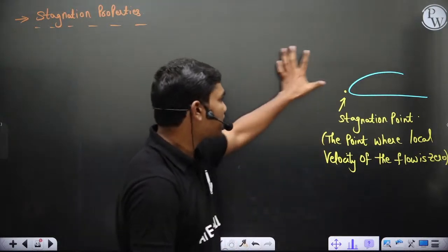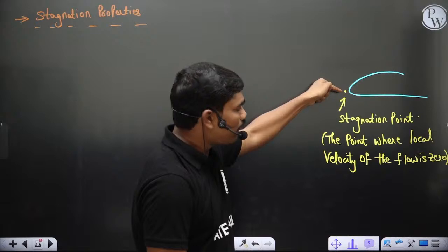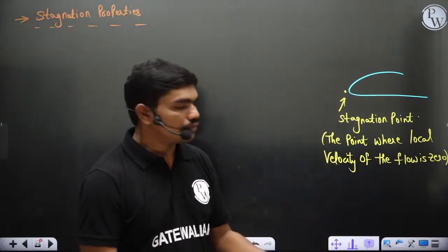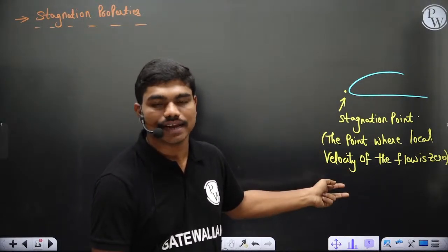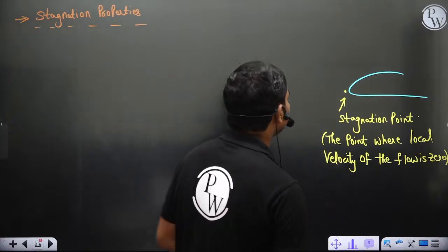Okay, so let's say there is some gas, for example, or maybe some liquid, whatever, some fluid is there. So at this point of stagnation, what is the pressure, density, temperature, specific enthalpy, all these things we call stagnation properties. Stagnation pressure, stagnation temperature, stagnation enthalpy, things like that. Okay, now let's see a few important things here.